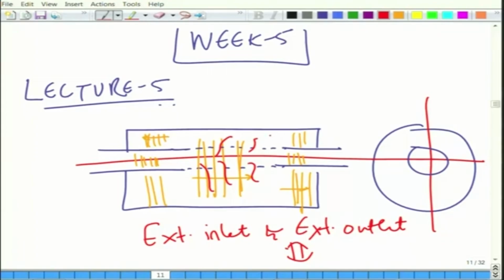We will probably talk about that when we consider perforated elements, very crucial parts of muffler analysis. Since we are discussing this, it was important to mention that systems like this are often connected through a perforated bridge, a highly porous perforated bridge. What it means is that mechanically the flow is allowed to be guided smoothly through the pipe. At the same time, the porosity allows the waves to very freely interact with the annular cavity, as if the perforated tube, the bridge, was not there.